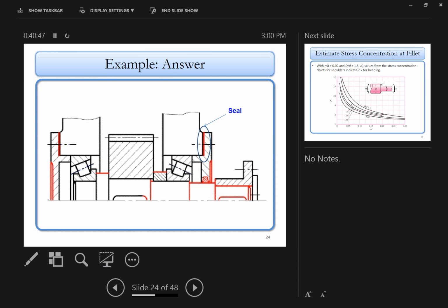In this configuration, should there be any room beside one of the bearings to account for any thermal expansion? It should. This is what we call a very rigid type of locating. So what I'm saying is not that it's not okay. For some scenarios, if you want a very rigid, very stiff type of locating, you can have both ends be locating bearings, instead of floating one end.